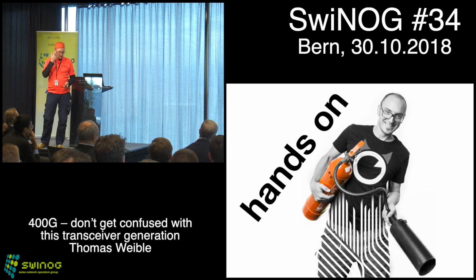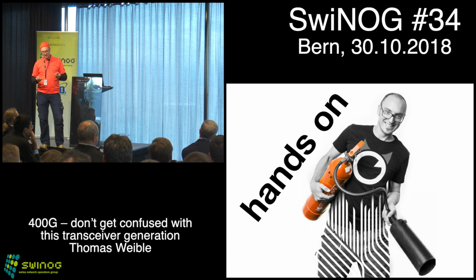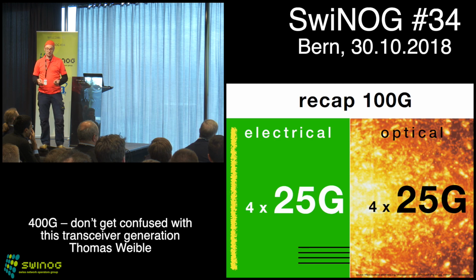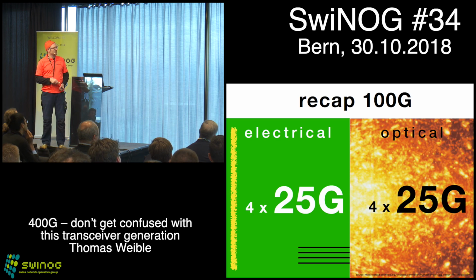Coming to the hands-on, this technology now needs somehow to be built up in a transceiver. And before I jump straight to those 400 gigabit transceivers, I would like to do a recap on the 100 gigabit, which is now mature technology, which has been around in the field for a long time. Opening up a 100 gigabit transceiver, we have mainly 2 components in there. We got an electrical side where our PCB is placed. We got the connector connecting to our host.